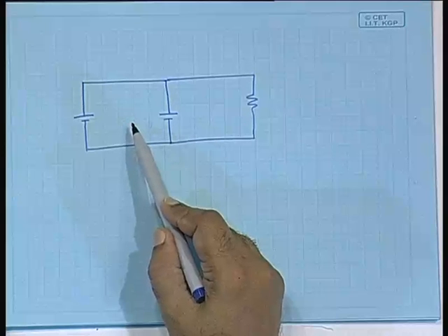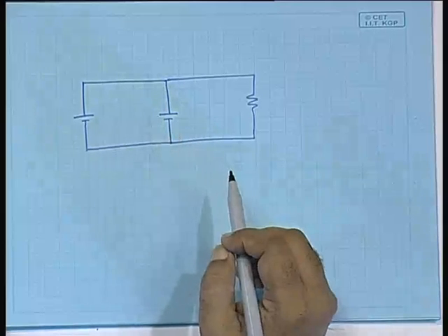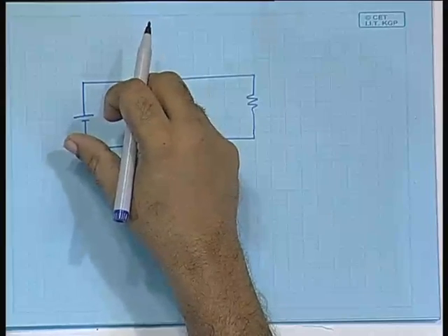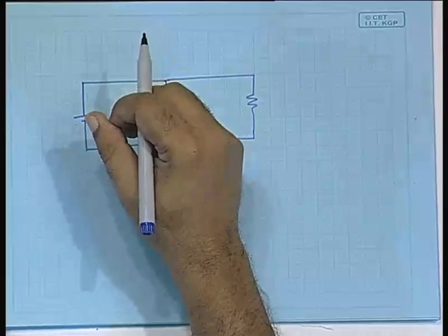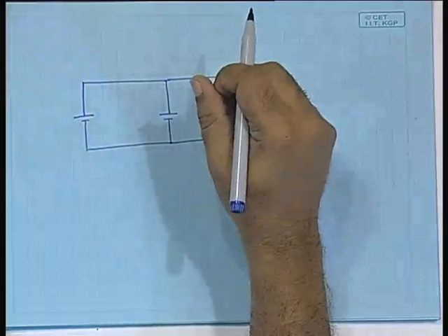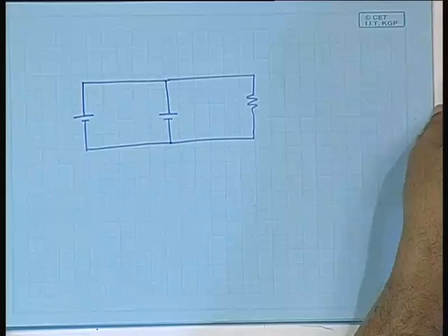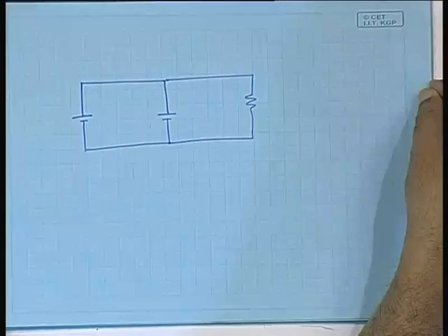It will result only in the heating of the two batteries, and naturally that is detrimental to the health of the batteries. So, this kind of problem also has to be avoided in case of photovoltaic cells, because it is very rarely the case that two cells are absolutely identical, producing the same voltage, producing the same current.